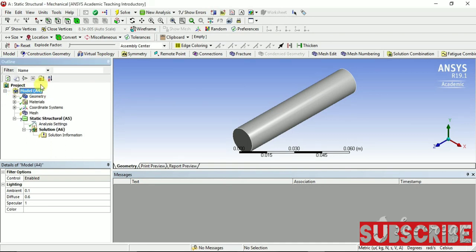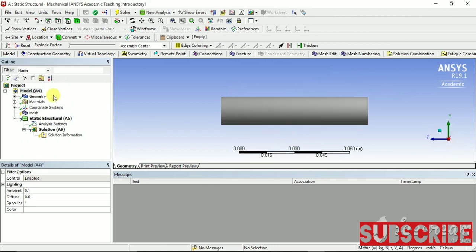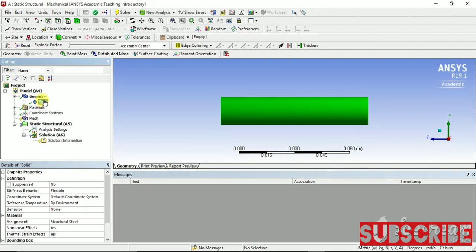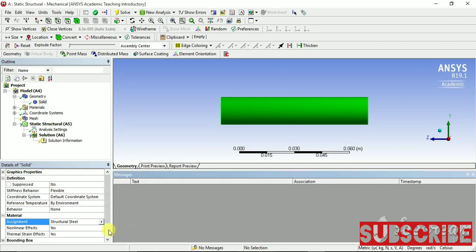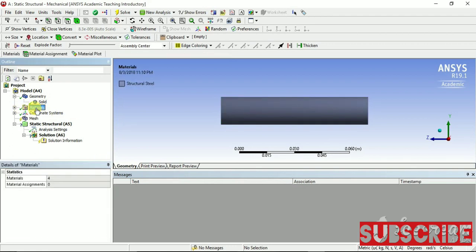Now from the start we will see what is done. In the Geometry section, click on the solid. This is the one body that is present. The assignment here is steel. We have added a few more materials, but I will keep it as structural steel. Now we have these materials that we added earlier in the Engineering Data.